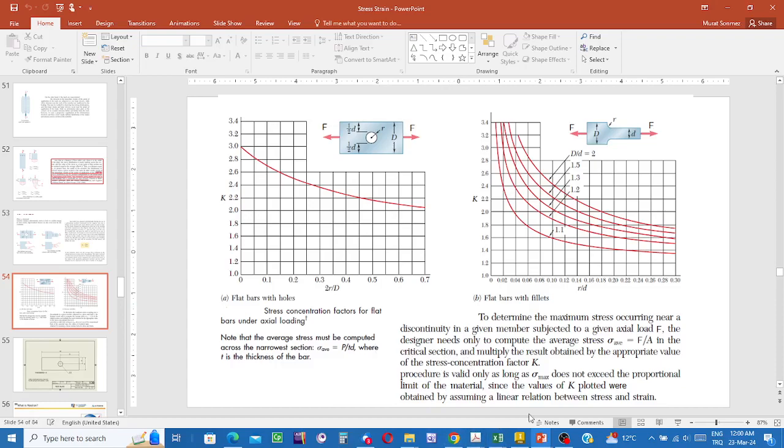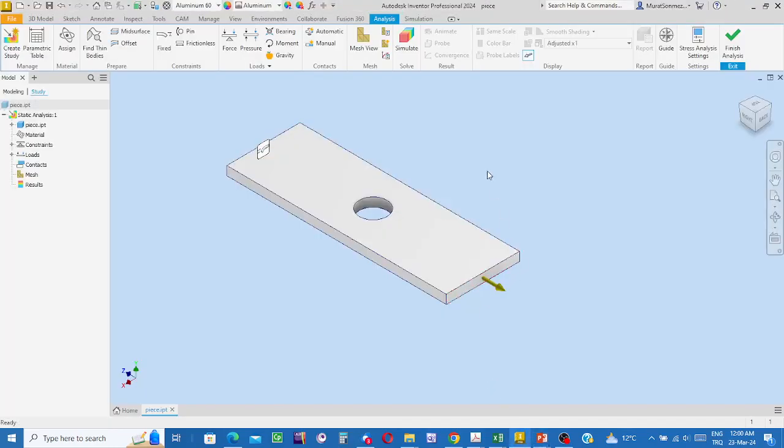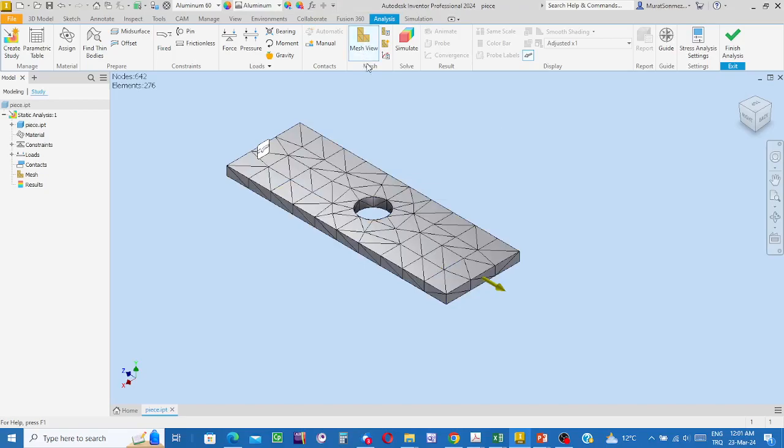Okay. In the vicinity of the discontinuity, I'm going to allow the software to use a finer mesh using the refinement technique. See how. First, create the mesh, discretize the body using the default mesh size. Here, at present, the mesh is an average mesh; all the finite elements in this mesh are almost of the same order of average size.